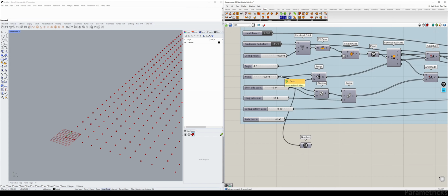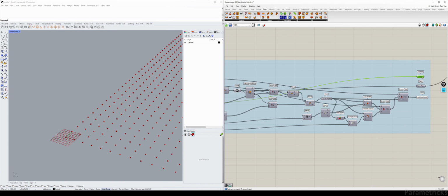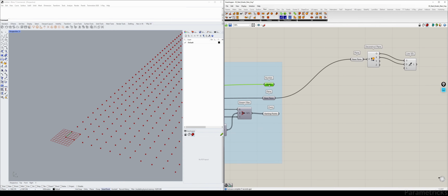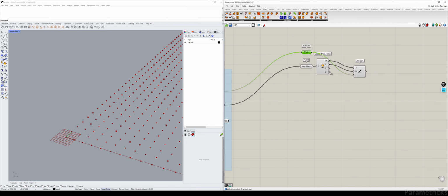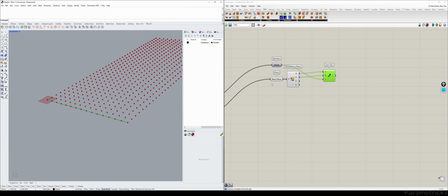Now, if you've forgotten, you can directly name this without having to type this in. It will take the name from the input. When you're dragging, press Alt one time. It will turn into a red arrow. If you plug that in, it will also take the name of whatever you're plugging into. Could save you a few milliseconds. So we're going to pick that in here. We'll move that here, and we'll give that, oops, we'll give that the length. So now we have our line.